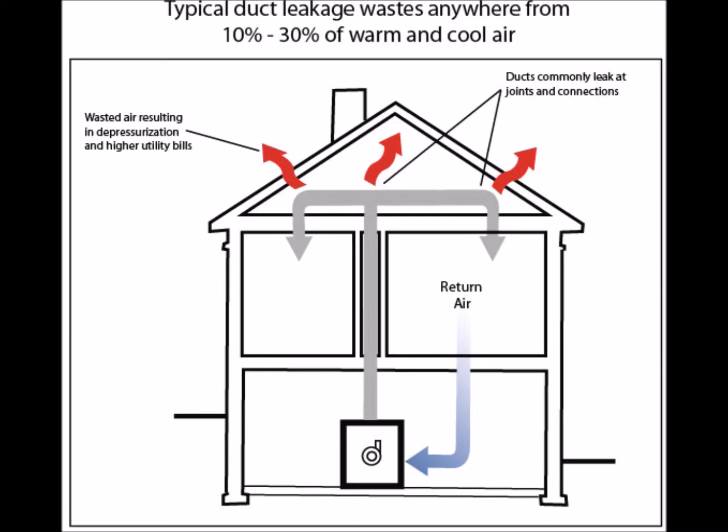might see furring strips attached to the underside of the rafter boards. These furring strips will provide enough room for thicker insulation to be installed. Some builders will install high-density batts in tight areas or add rigid foam insulation under the rafters. Rigid foam insulation is a good choice because of its ability to resist thermal bridging through the rafters.